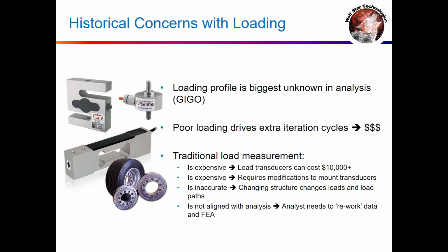So traditional load measurement can be expensive. It will use tools like you see on the screen here. These are standard load transducers, and these are fine, but every time you introduce a load transducer into your system, you've got to cut away part of your system, introduce the load transducer, and then reinforce it. So now you've changed the masses, you've changed the load paths, and you're measuring something that may or may not be